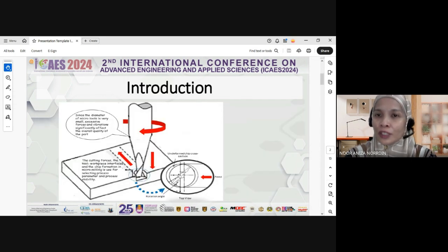So a little bit of introduction on what is the micro milling process. Micro machining is a process of producing miniature products and components with features that range from tens of micrometers to a few millimeters in size by removing the unwanted material from the workpiece using the mechanical force of a micro tool. The mechanical micromachining is basically not a downscale of the tool size and the material removal from macro milling. There is a point of limitation on the scale down procedure.